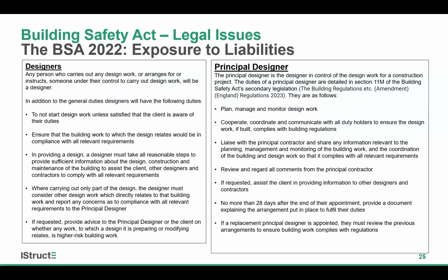But as a structural engineer, you may also be the principal designer. And the principal designer is appointed to coordinate the design work, manage and monitor the design process, and ensure overall compliance with building regulations and safety standards. So whilst the individual designers are responsible for compliance with their specific design work, the principal designer takes on a broader coordinating role regarding the wider design. So there's no doubt that as duty holders, both the designer and the principal designer have extensive statutory obligations and responsibilities, each of which creates additional risk, liability, and exposure.